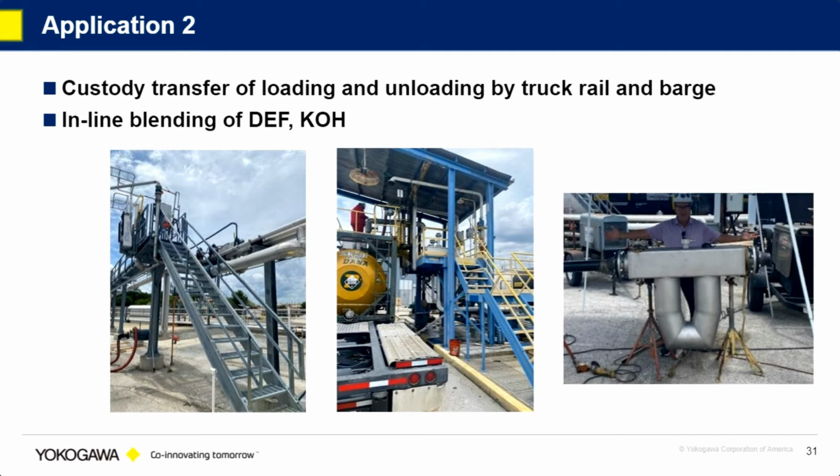So we were asked to keep this under an hour, and we could take any of these topics and probably go pretty deep with it for 3 or 4 hours. My experience has been most people go to Coriolis meters if it's liquid service because the fluid is non-conductive, and they may calculate volumetric based off the mass and the density, but the other driving force is whether or not it's custody transfer. It's a recognized technology for bill of lading purposes, both in liquid and gas.